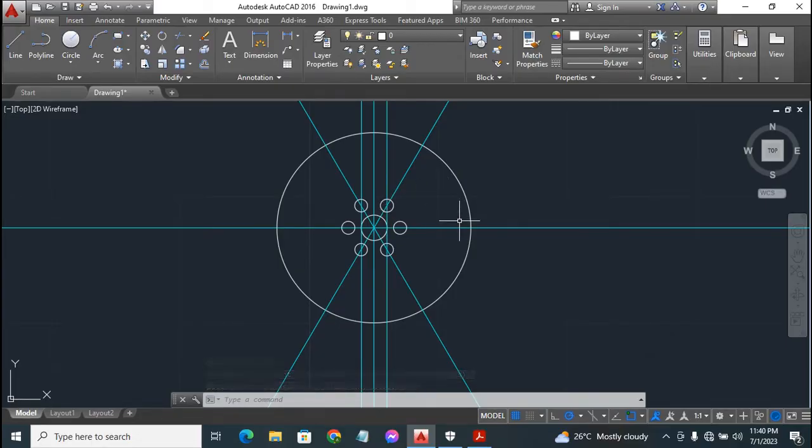Now you might want to ask, why are we not using the array tool? If you use the array tool, you will not be able to trim out some part of the circle, because whatever change we make to any of the circles will affect the rest. So that's why we are not using the array tool. I know you might be tempted, wondering why we are stressing ourselves drawing these circles one after the other instead of simply using the array tool. I've given you the reason, so don't be tempted. Just follow my instructions and you won't be frustrated while trying to do this.